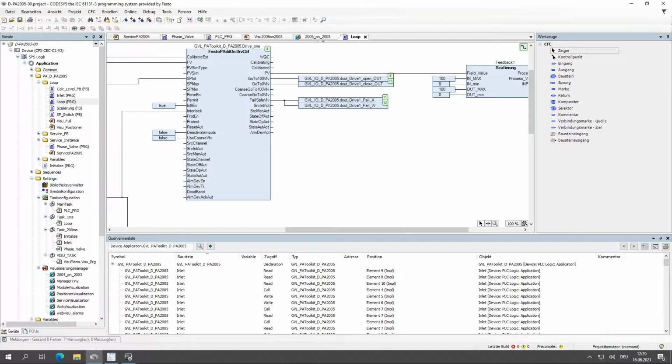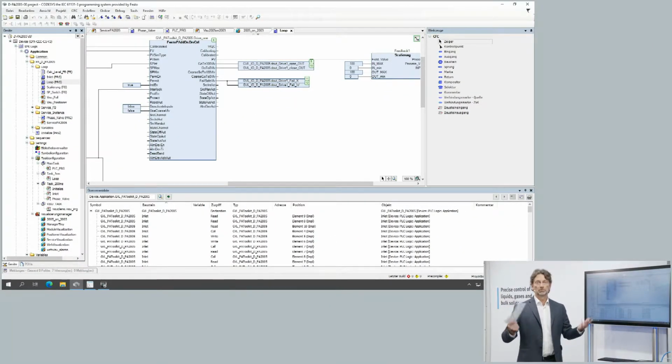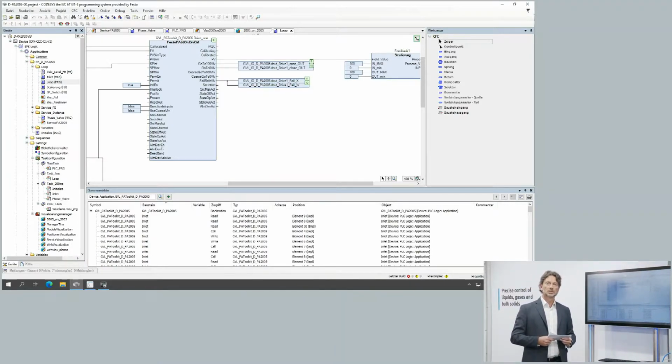These are mainly parameters that are being used to tell this function block what it is meant to do. By telling it, for instance, that the units are Celsius degrees, you define this function block as a temperature sensor. And if you tell it that it should use, well, liters per hour, then it is clear that this function block is then later on, in the field, actually a flow meter. So these are the function blocks, or one of the function blocks, that we have in our library.